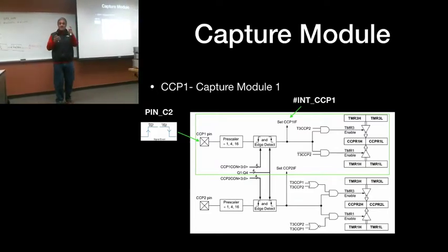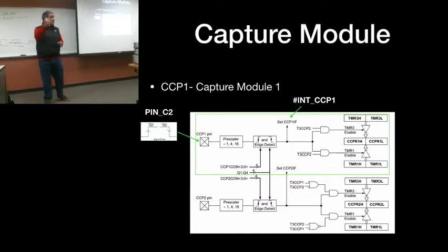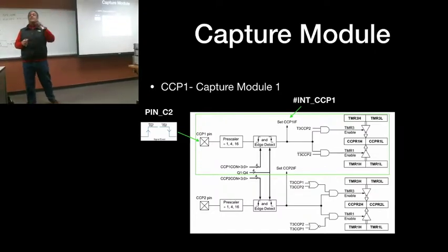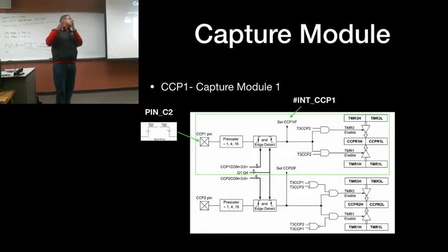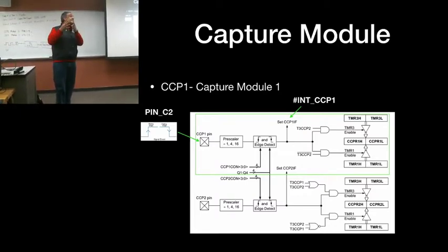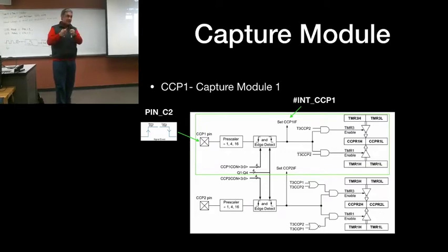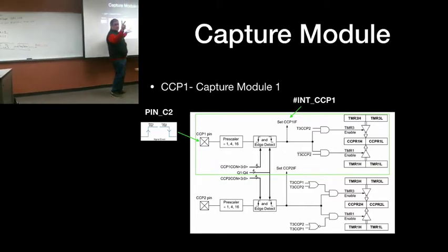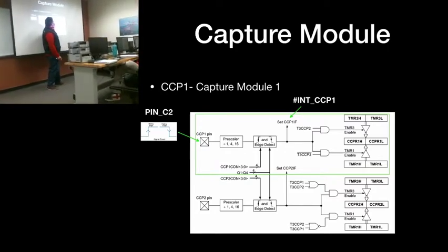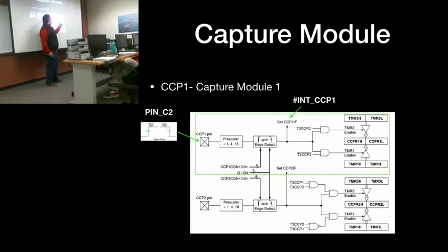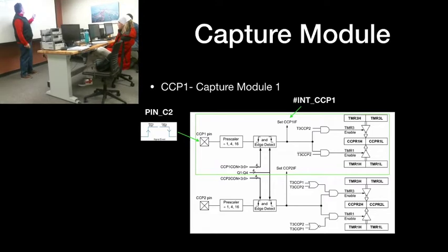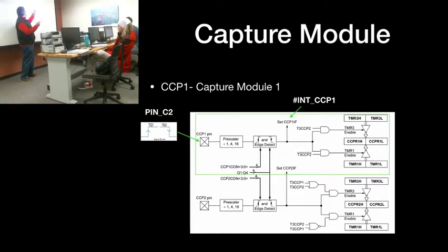In this event, it's a little bit different. You press a button, an edge gets detected, the microprocessor is going to interrupt, but it's going to now save the moment in time that this event was detected. Okay? So how does the machine do that? Well, you have two choices. You can either configure your system to work with timer 1. We already work with timer 1. Or you can use the system setup for timer 3.